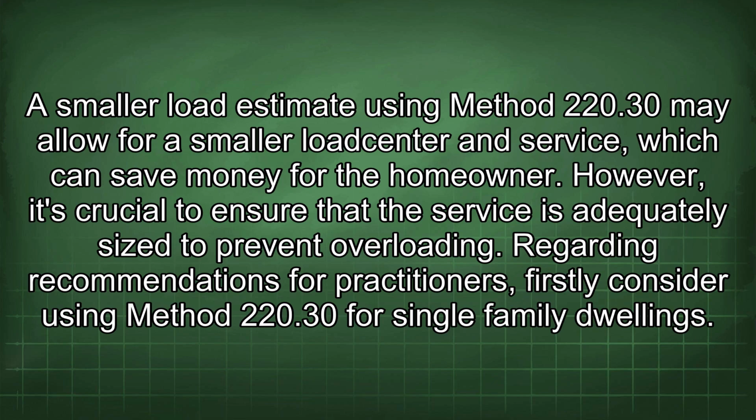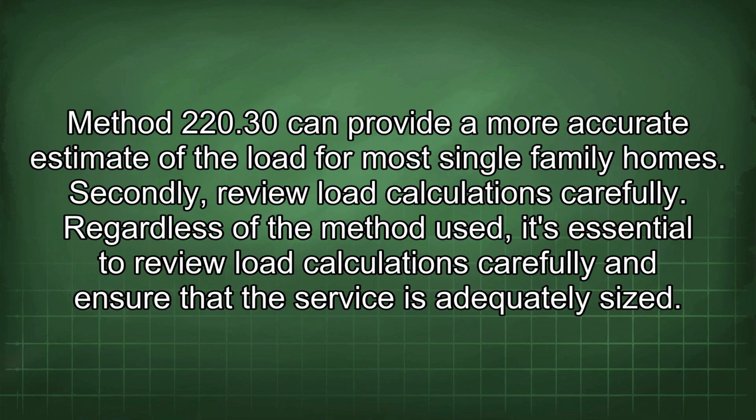Regarding recommendations for practitioners, firstly, consider using method 220.30 for single-family dwellings. Method 220.30 can provide a more accurate estimate of the load for most single-family homes. Secondly, review load calculations carefully. Regardless of the method used, it's essential to review load calculations carefully and ensure that the service is adequately sized.